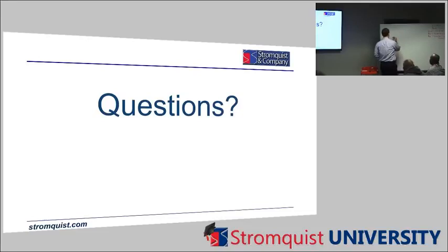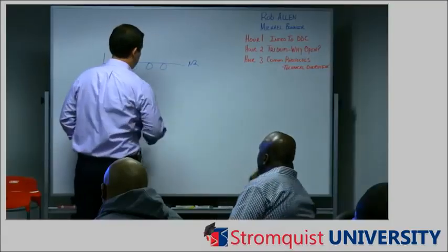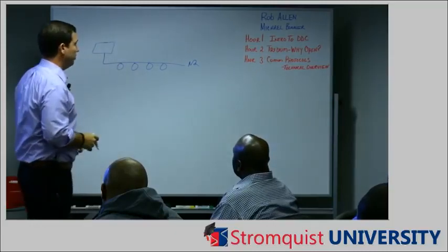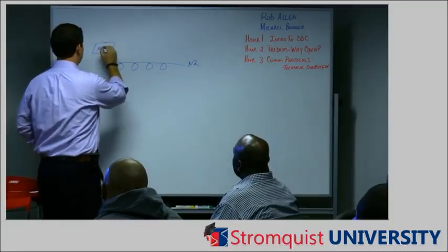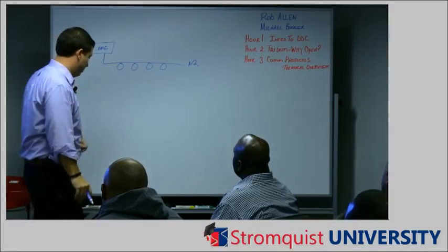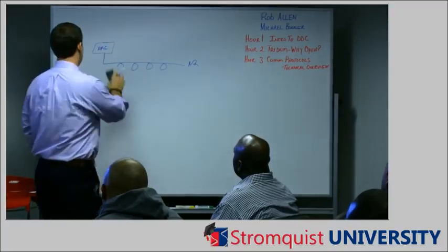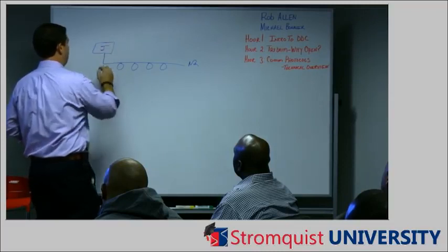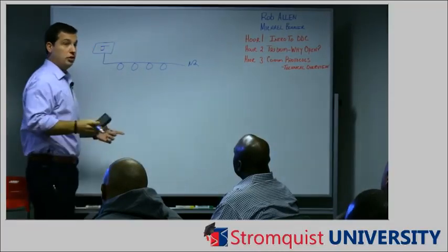So what we're going to do is we're going to have, and this is going to be a really crude drawing, okay? So we're going to have, this is our N2 or our Metasys, right? And we've got our controllers on here in our building, and then we've got their head-end somewhere. It's probably called an NAE. All right, so what we would do is we would do away with that NAE, and we would install our Jace. And our Jace would pick up all of our N2 in there, so we're good to go.